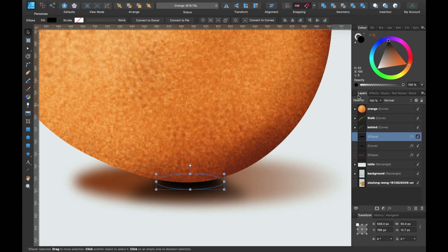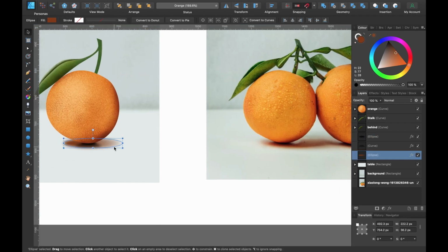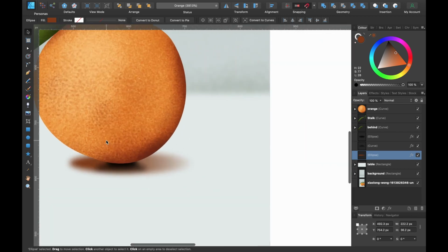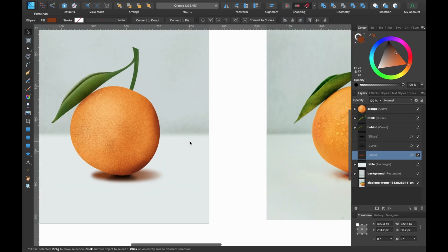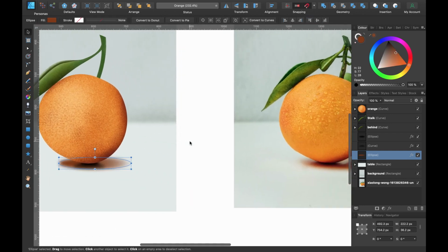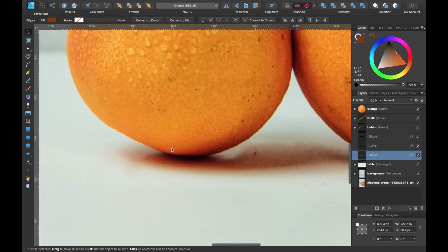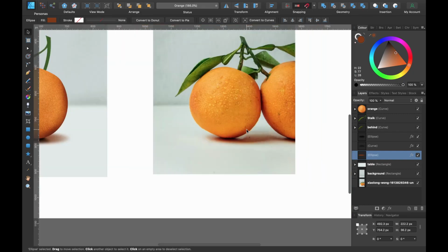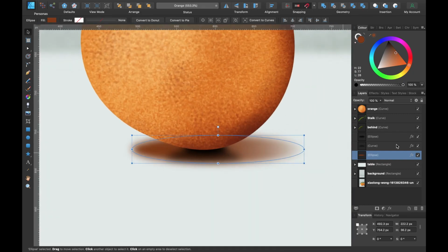and it's just about building up these kind of layers to give it that effect. So looking at this shadow and this one, it's a bit light on this side, so I'm just going to hit the transparency tool again and push this slider up to the right a little bit more. Okay, so we've got our basic shadow here. You can see it's a little bit lighter. If we go to this one, it's a little bit lighter up here and a bit lighter here as well, from maybe the light behind the orange. So I'll just recreate that as well.